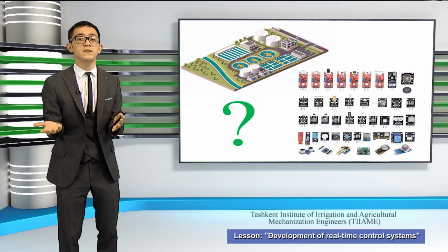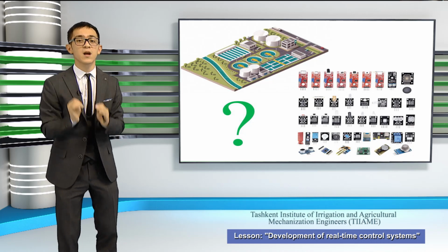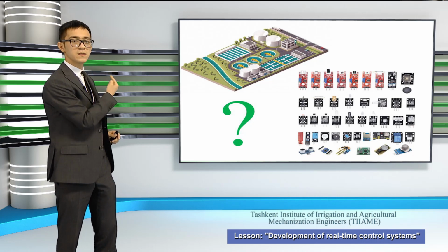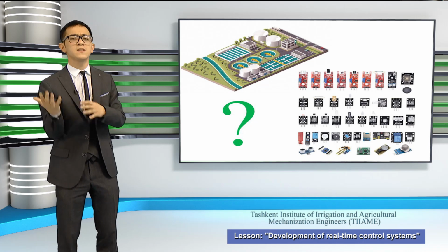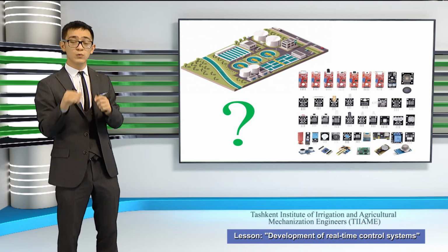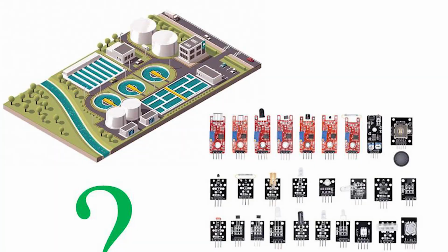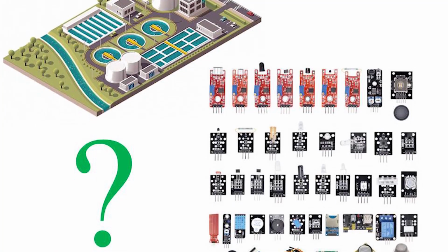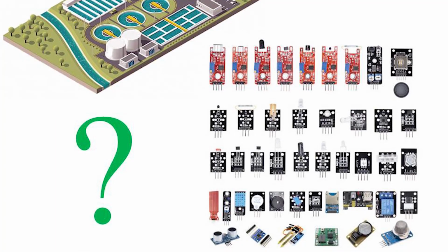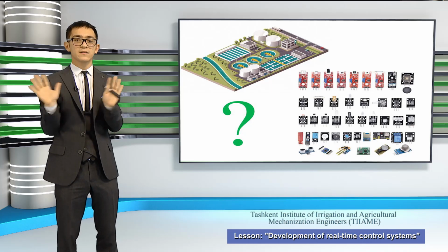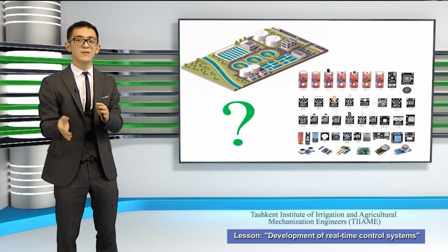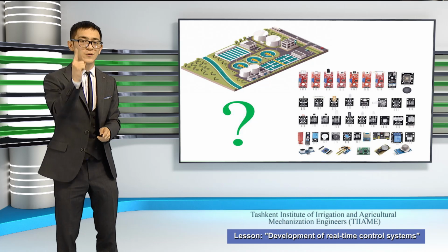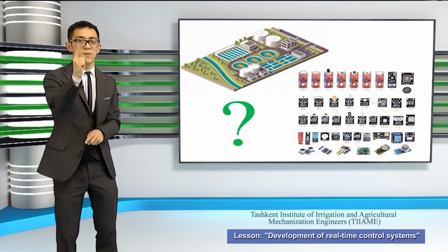According to this characteristic, you select the correct sensor. Here you see a lot of typical sensors. There are more than 50 types of modules. What is a module? A module is a special tool to take the analogous signal of a sensor and convert it to the needed value for your computer. If you choose an incorrect module, the measurement is incorrect and your technology process is dangerous. So first, we need to understand using correct sensors.